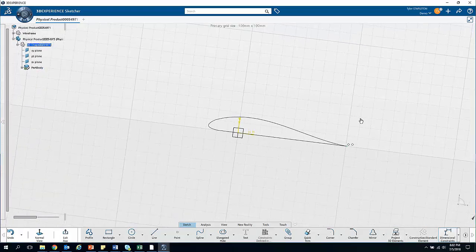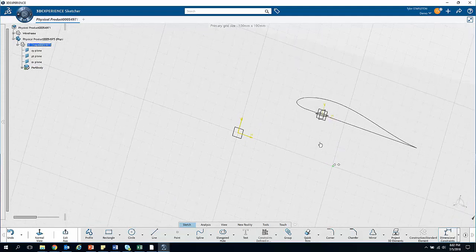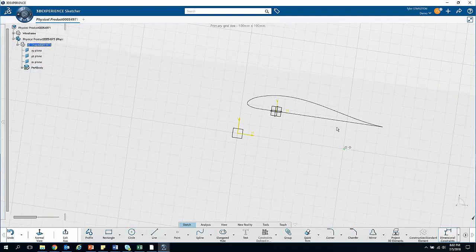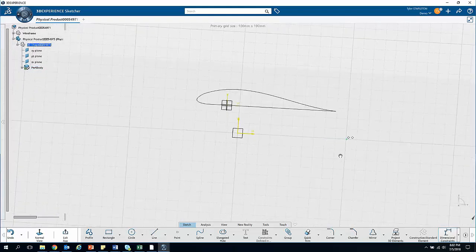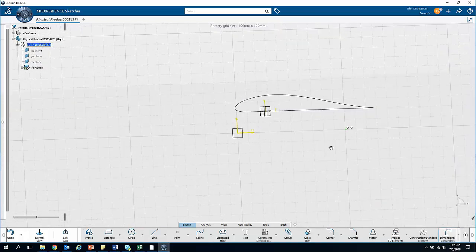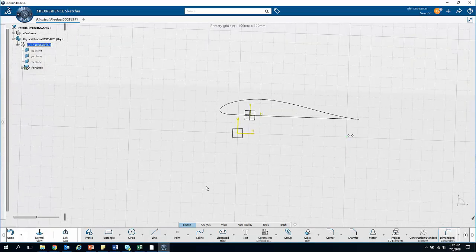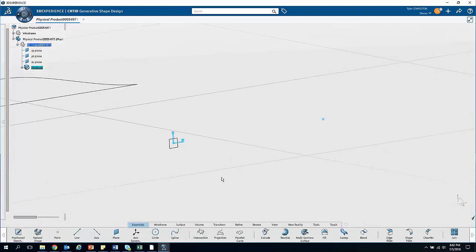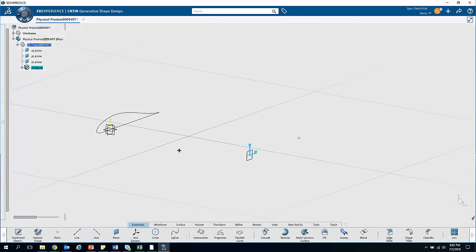And what you can see now, if I can tilt this, is these points actually now line up on top of each other. Essentially, they're as close to each other as I can get while still being on two separate planes, meaning that they will line up perfectly. I can put that back in normal view and you'll see those line up. Alright, so I'll exit that sketcher, and now I have everything set up so I can transform our old